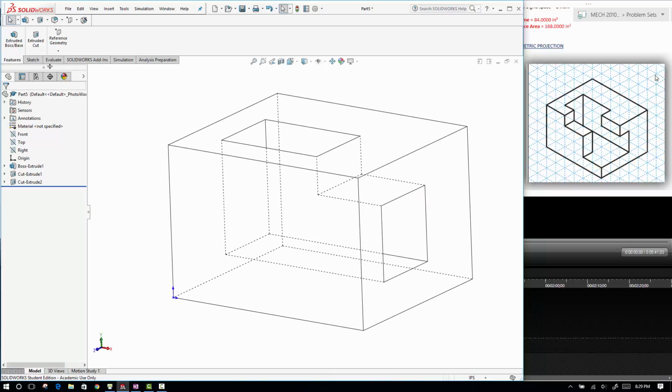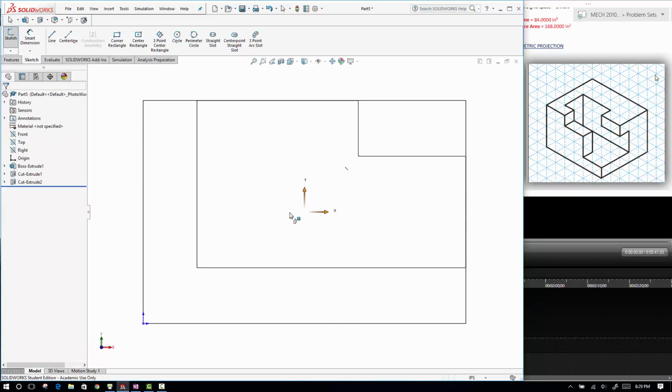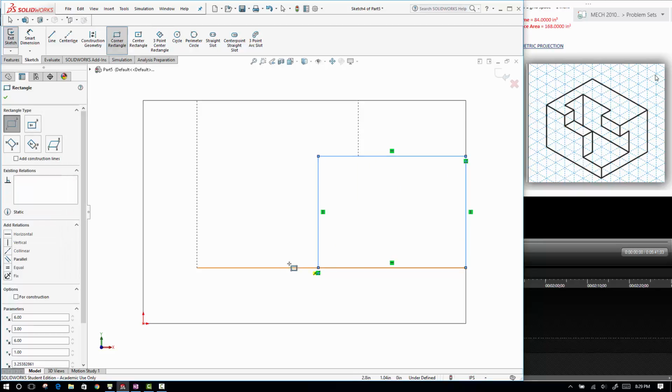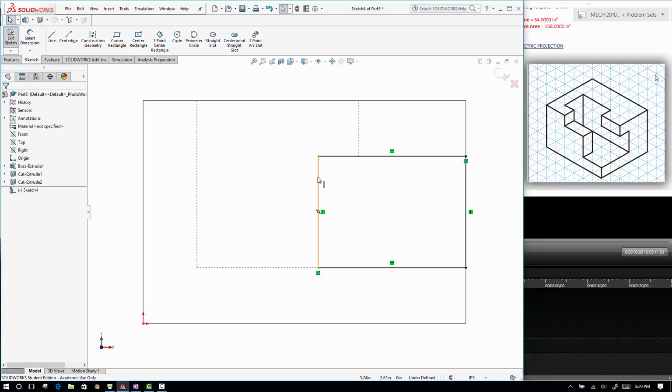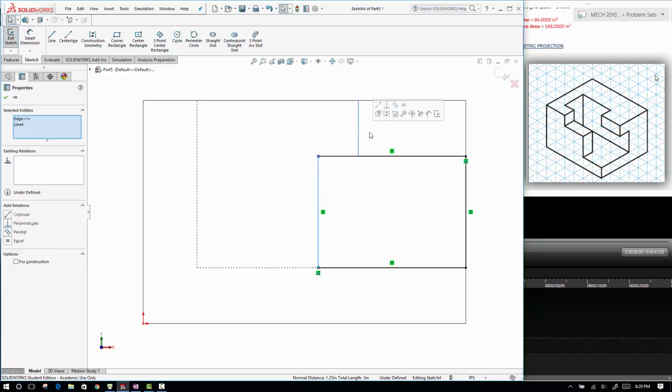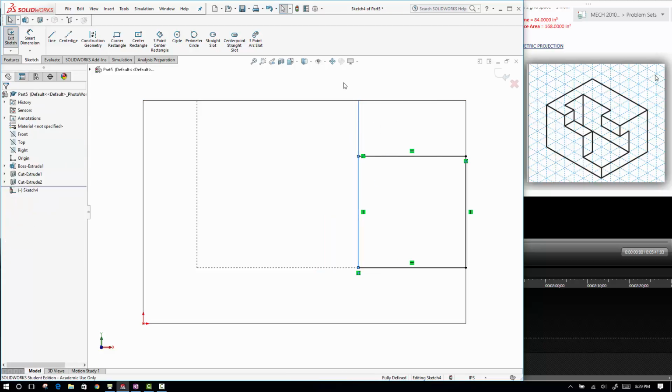So now I'm going to again use sketch, and I'm going to sketch on this surface, and this time I'm going to remove this square. So I'm going to select this vertex, come down and make sure I grab this edge somewhere so that I'm coincident to it. And I purposely went long because I want to be able to use my control key to select these 2 edges and make them collinear to each other.